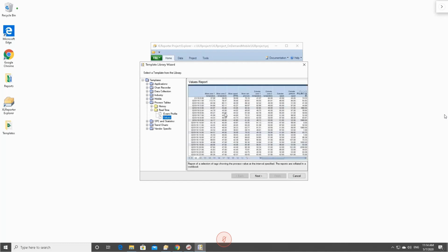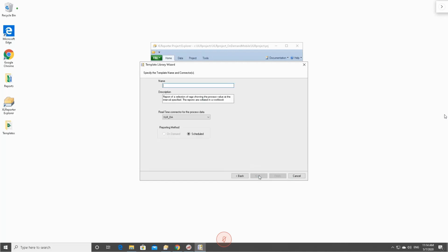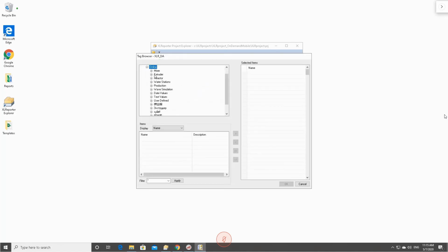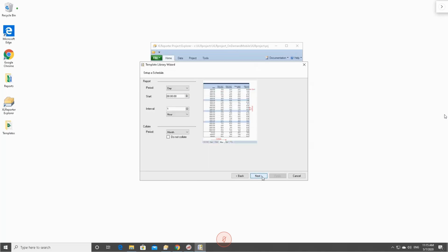Here, just to show you guys a tabular basic report to schedule it, we can call this one 15-minute turbidity. We'll use a scheduled definition here. For a scheduled report, you basically just have to include the tags in the configuration since they have to be known at runtime. For example, I would want this report to collect new data every 15 minutes over the day.